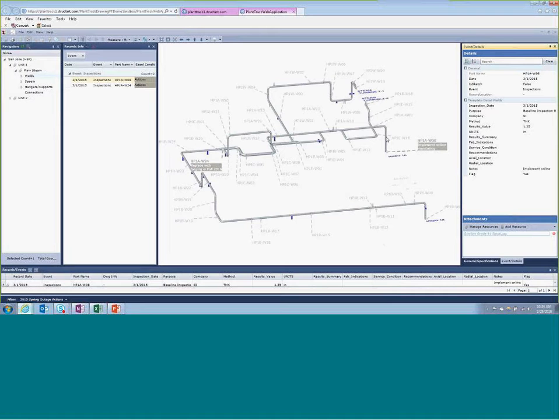And that's really important. So you take things like, for example, component geometry, in this case the spool. The wall thickness is globally low, so we take it into account. All things like material conditions, again, low hardness. So we're then able to calculate a level of damage, and you can try that into the future.